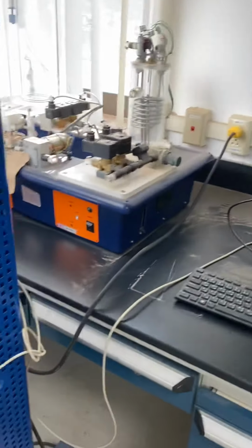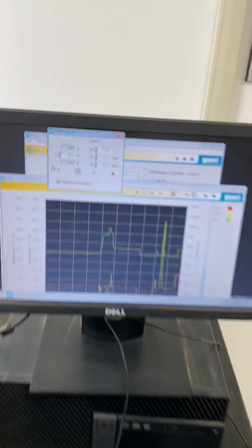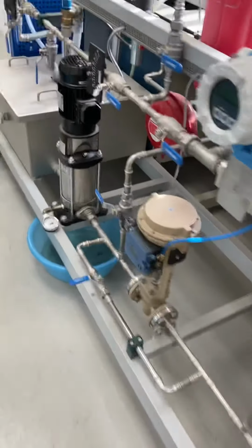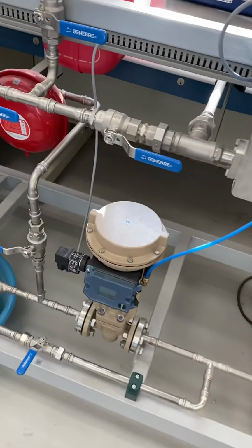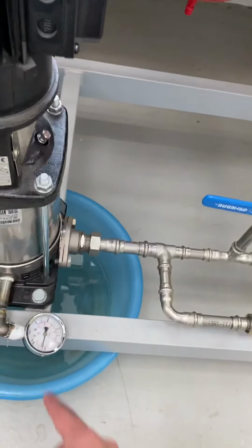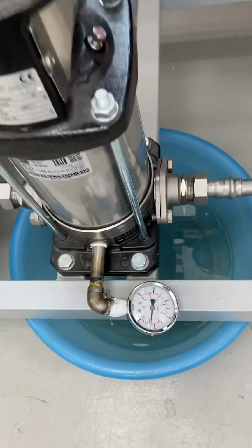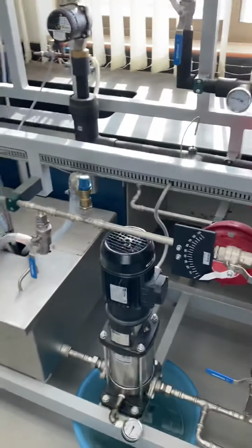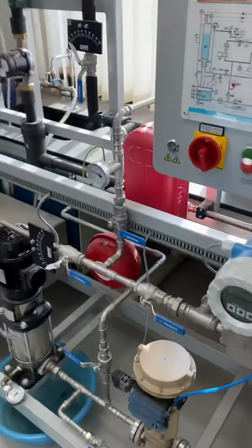The more we open the valve, the more you increase in here, guys, the more you increase the output signal, the more you open the valve. This is a fair closed valve, and the more you open the valve, the less discharge pressure you get. That is true for fixed speed pumps.